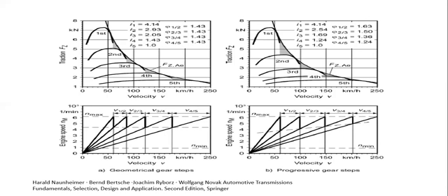So you have alternately easy splitter shifts without main shift lever movement, and compound shifts with splitter and main box. The range change unit, which is also called a large gear step, means that you have to go through the gears of the main gearbox twice in the upshifting procedure, first in low range and again in high range.